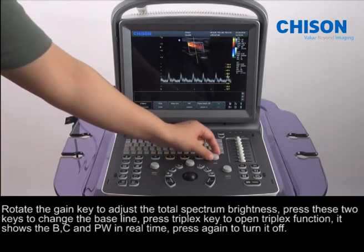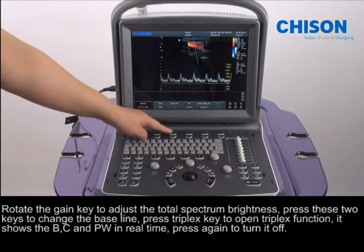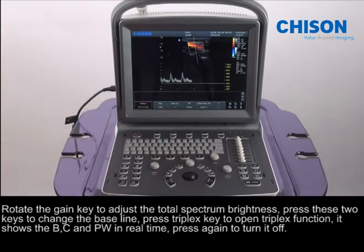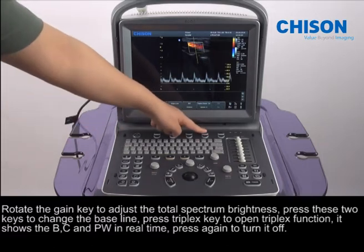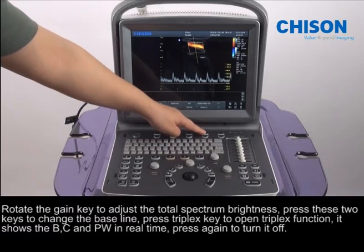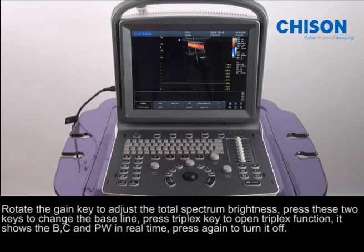Rotate the gain key to adjust the total spectrum brightness. Press these two keys to change the baseline. Press triplex key to open triplex function. It shows the B, C, and the PW in real time. Press again to turn it off.